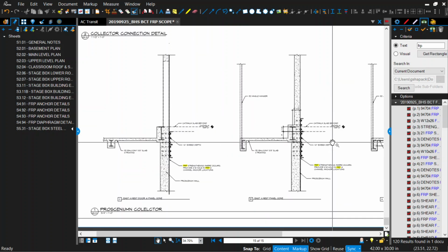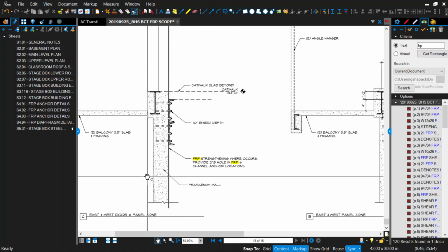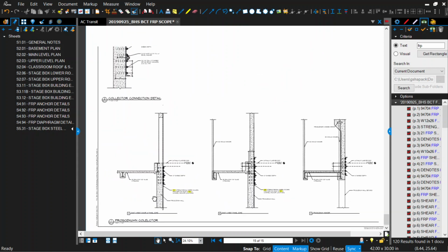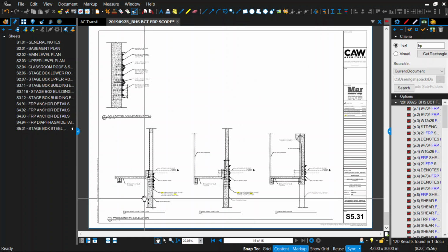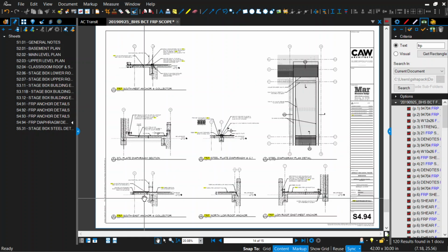Okay, but anyway, seeing what you might have to do on this job, because the 37 kips per foot for shear transfer is really, really high, we'll have to do mortar ramps to make it work, like the collector. I don't know why I'm trying to draw in the air, we have a whiteboard in here, I should just go use it.